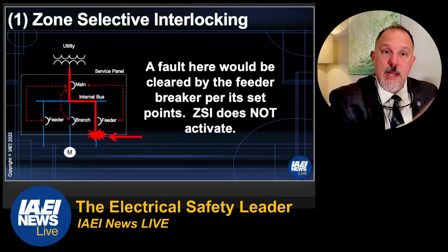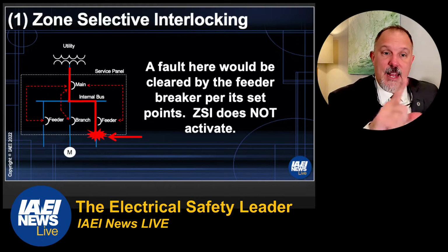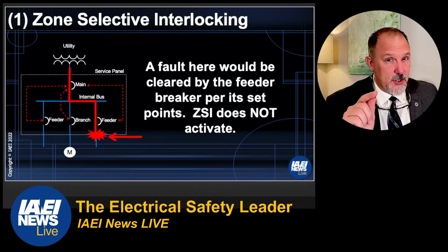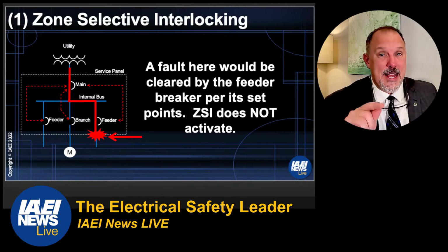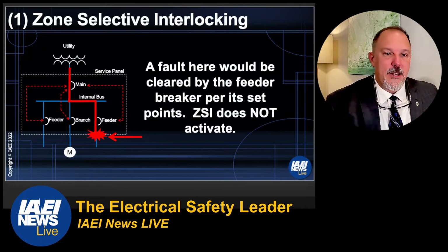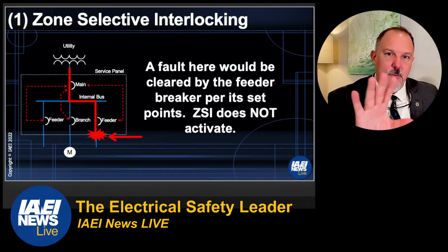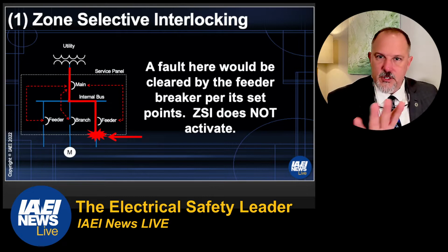So both the main overcurrent protective device and the feeder see current beyond the pickup points that you've already programmed. And I'll tell you what it triggers off of is the short time delay pickup point. And if you remember, I'll show you that trip curve and I'll show you that pickup point here. Just give me a second.